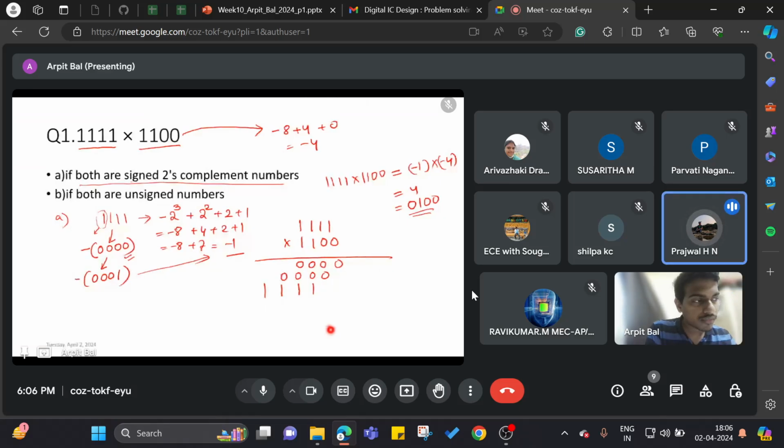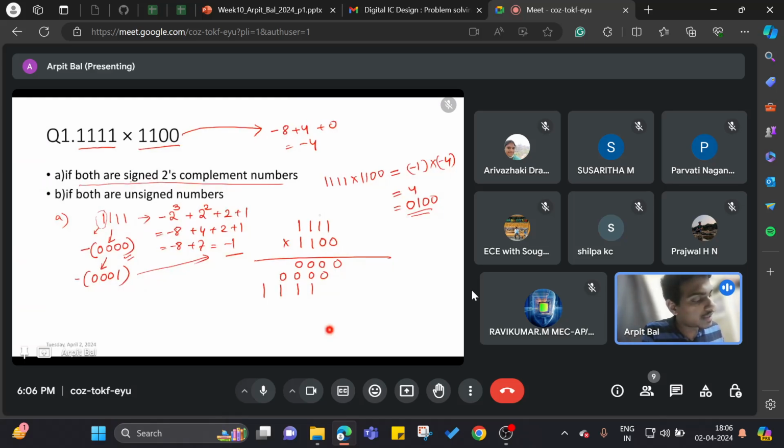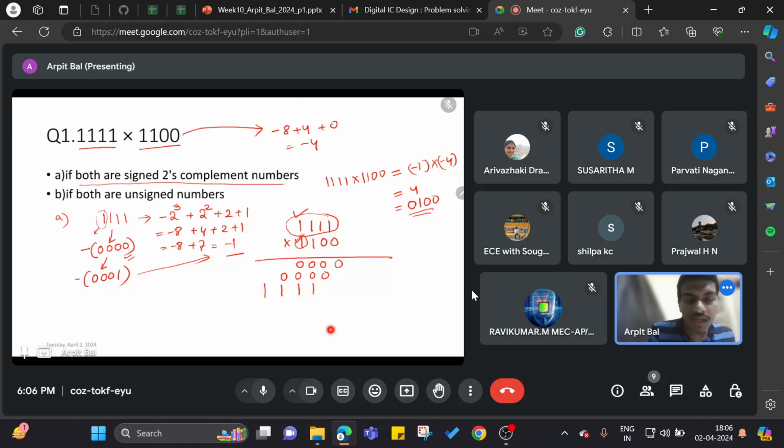The first 3 bits are negative. The last MSB is positive. So what is going to happen is, we basically multiply this with this. This is already a negative number. Okay, and if we are multiplying with this, then it will become a positive number altogether. So in this case, we should not write 1 1 1 1. Okay, it should be the positive form of that 2's complement.